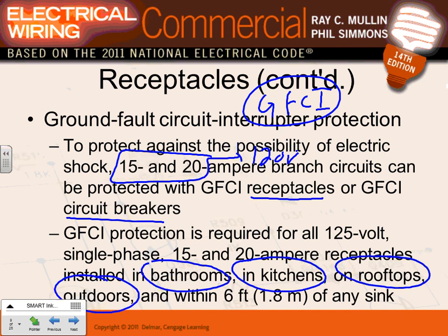Outdoors. And within 6 feet of any sink. These are your locations for GFCI receptacles. Any question, guys, about this? Now, here's my question for Kerry, my friend. Suppose that you have a mechanical room.